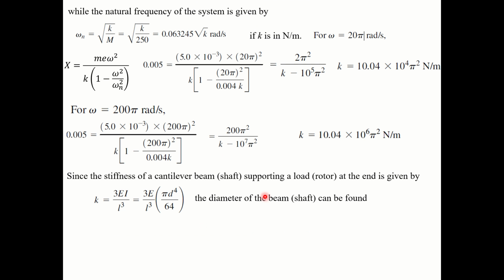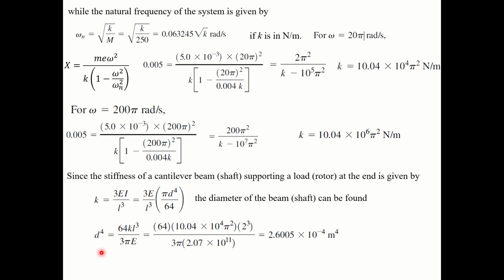So it is given as steel. Steel shaft. The material is given in the question, that is steel. That's why we are going with the 207 GPa. Steel Young's modulus, you should remember that. You take around 200 or 210 something, or you take 207 only. I think you have used the same thing in design of machine elements, in 2 also, in 1 also.